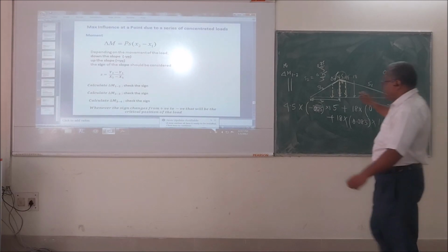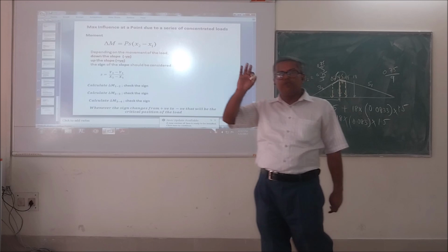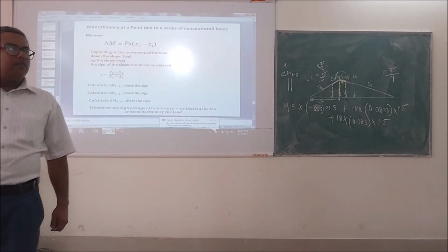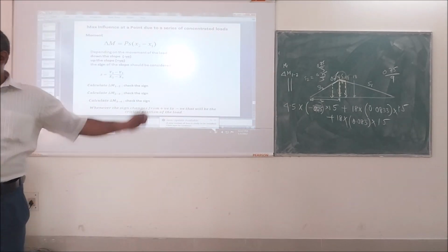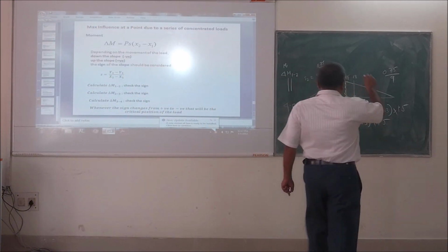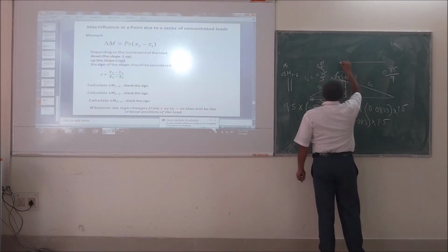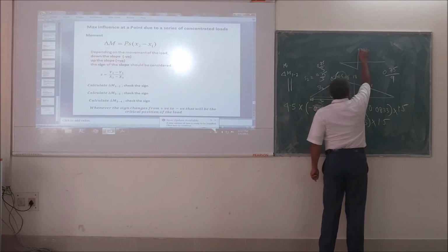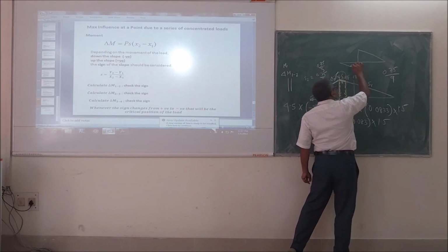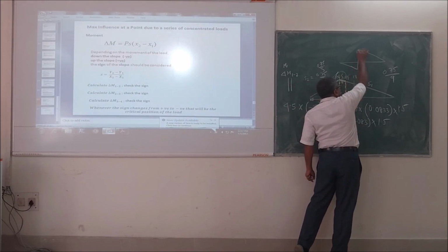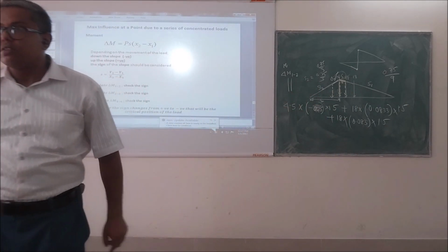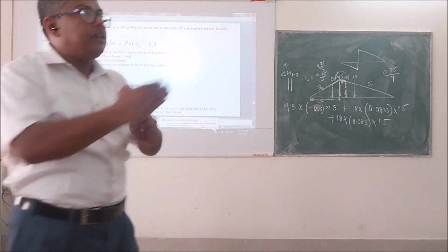Okay. So this is the process you have to follow. What you have done for shear force, the same thing is being done for moment. Only, in case of shear force, try to understand the difference. You had this kind of influence line diagram, right? When the load was moving up this slope, there was a drop from this to this. So that is why there was a -1 multiplication with the load, because there is a drop happening. After that it is rising up the slope.